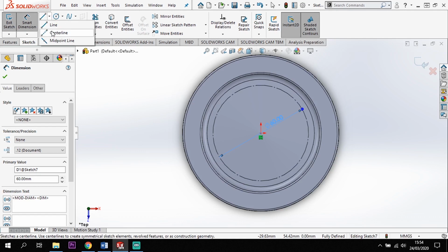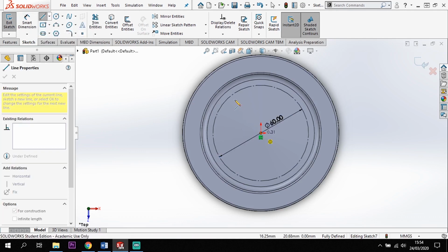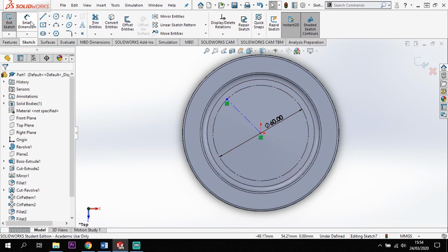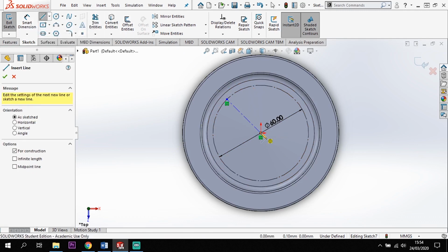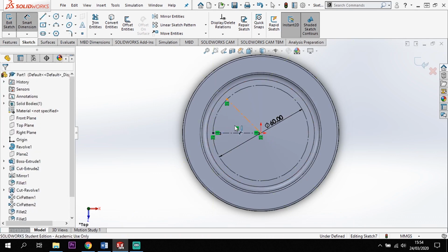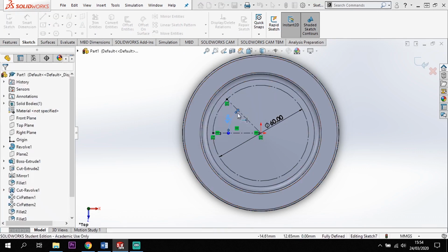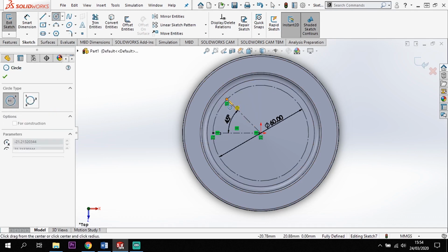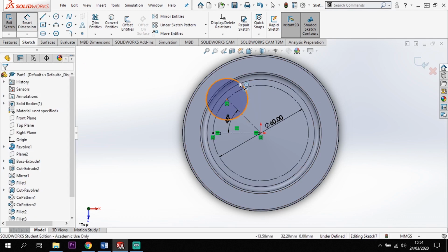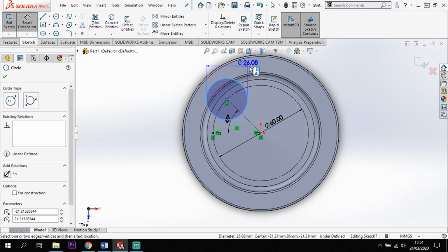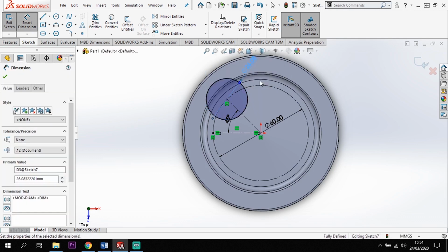Now with a centre line from there, I'm going to come out to 45 degrees, like so. Put another centre line in coming to this across, and I can just make sure that's dimensioned up and fully defined. 45 degrees there. Lovely. Okay, and at that point, I'm going to put a circle, and I'm going to dimension that to 30 diameter, like so.